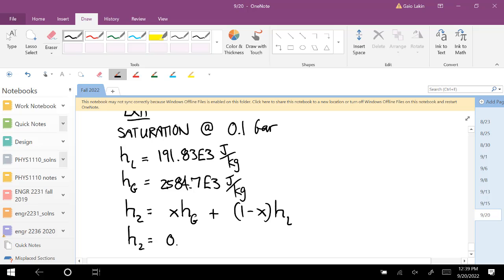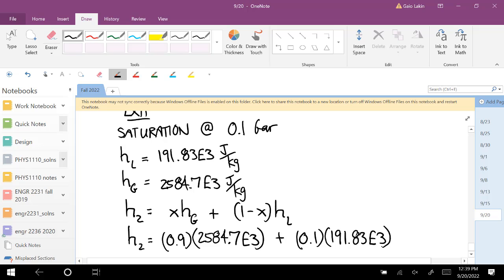So H2 is 0.9 times 2584.7 times 10 to the third plus 0.1, that's the 1 minus 0.9, times 191.83 times 10 to the third.